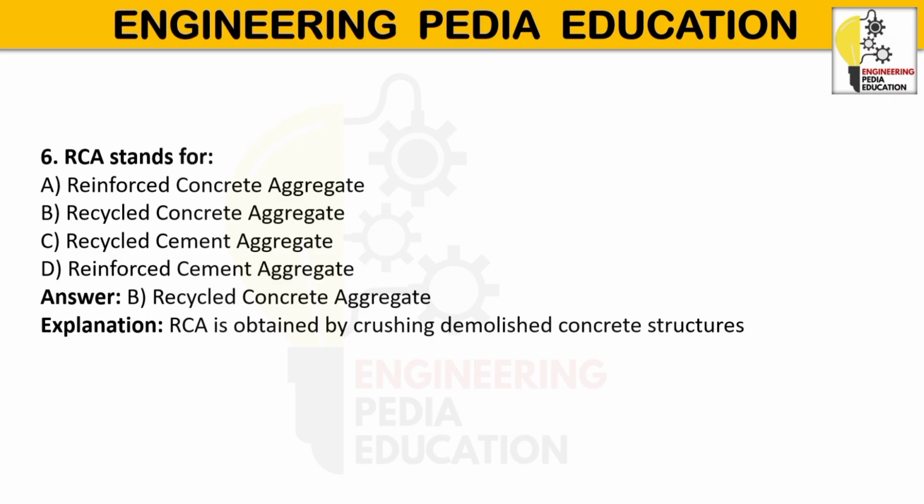Advantages are reduced construction and demolition waste, conserve natural stone resources, can lower material cost, support sustainable and eco-friendly construction practices. Limitations: high water absorption may require mix design adjustment. Quality can vary depending on source material. Additional testing is often needed before structural use.